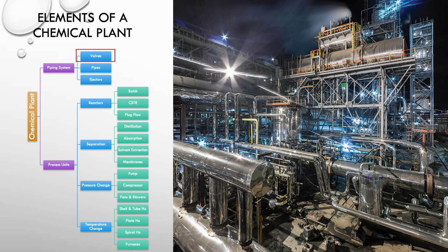For separation, that's pretty much any type of physical process that separates two or more components based on a given physical property. If we're talking about relative volatility, that will be distillation. If we're talking about relative solubility in a third fluid, then we're talking about solvent extraction.